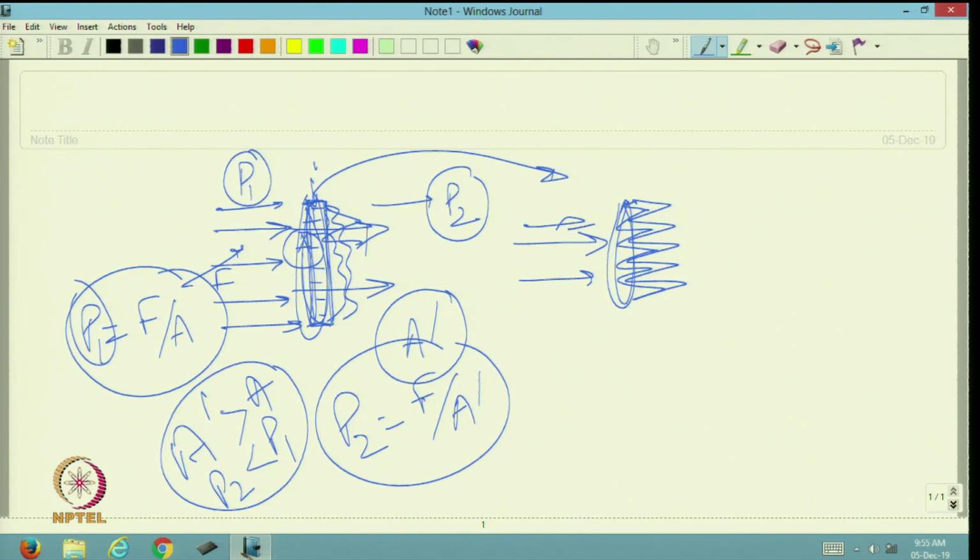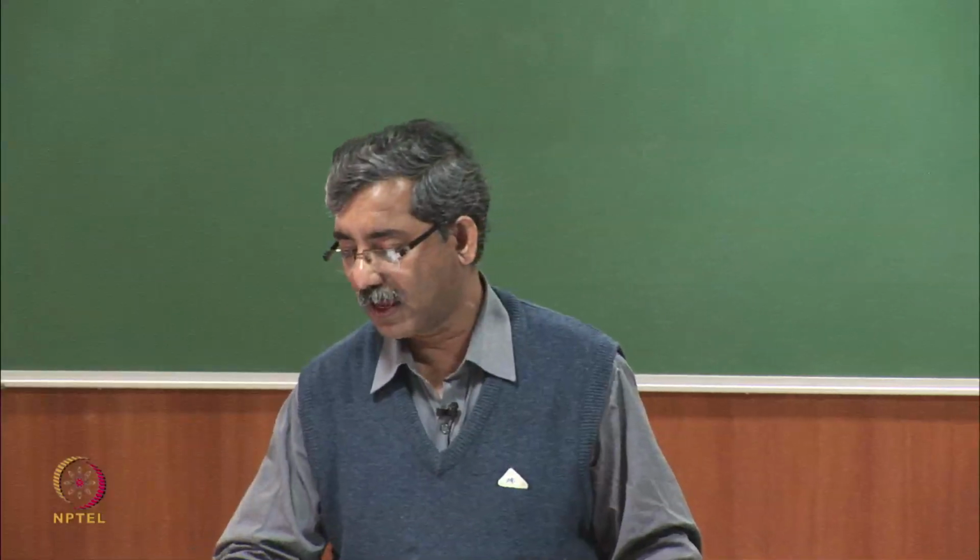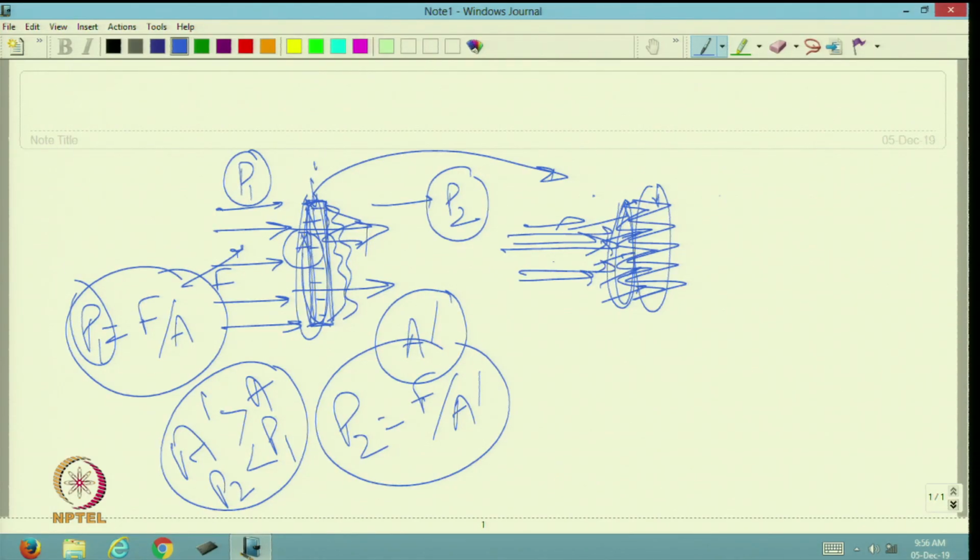So, the actual area of filter fabric has increased, therefore, the pressure difference between the upstream and downstream side has reduced, and as the actual area of the filter has increased, we can have the air flow rate higher, at a higher rate air can flow.